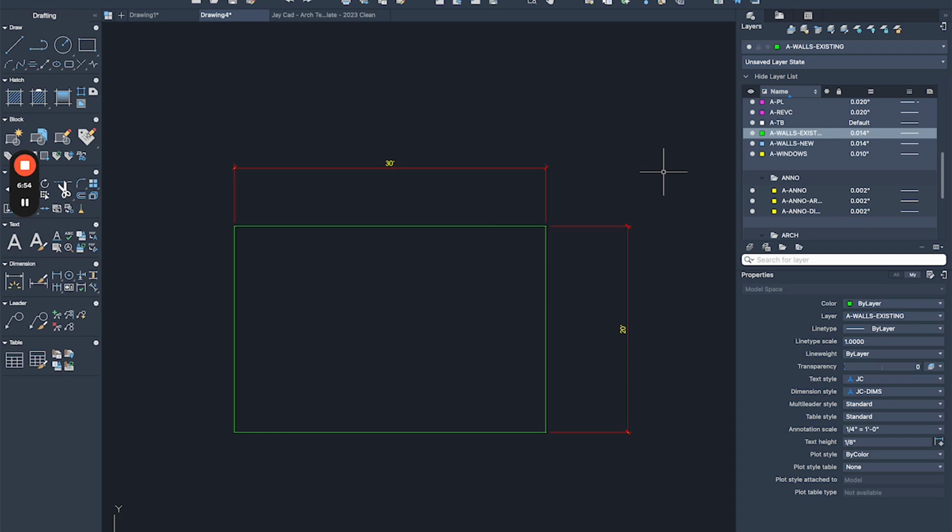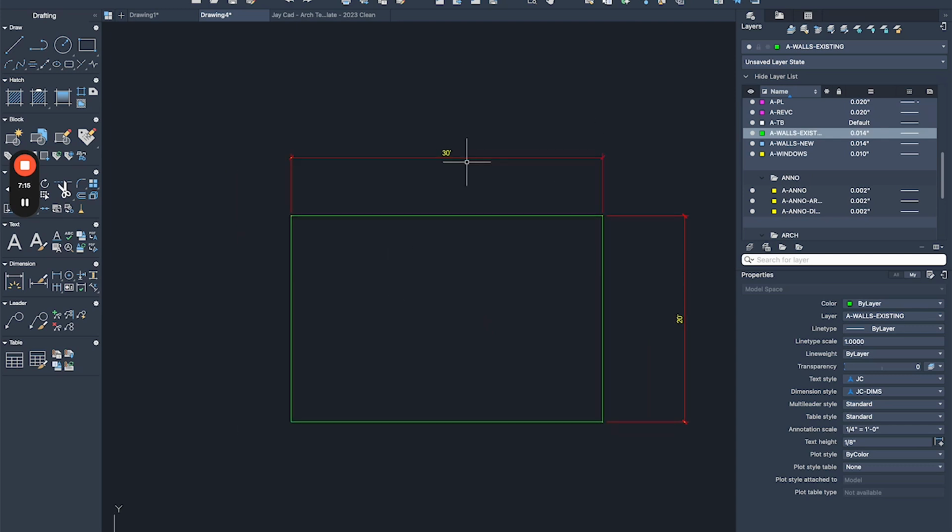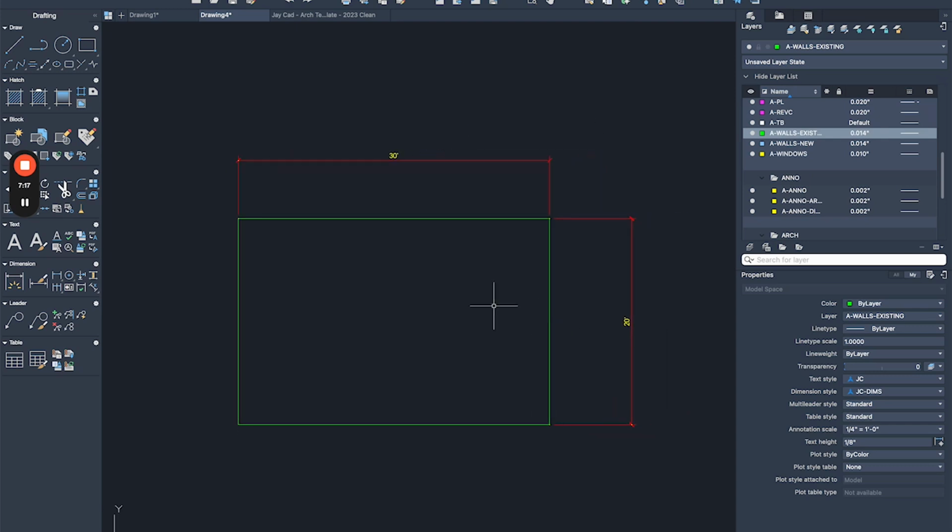and you do your drawings at the end of the day because you're going to send this to people to build the building, and you want to make sure that your notes and your drawings are easy to check by the city, by a plan checker, by another engineer or another design professional, and also by the builder on site. So you want to remember this as the purpose of your drawings. Make it easy for everyone. Now, back to our drawing, I've put the dimensions, I explained about scaling, so we can continue. Now I will do a little offset.